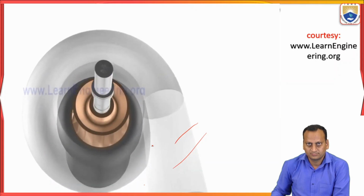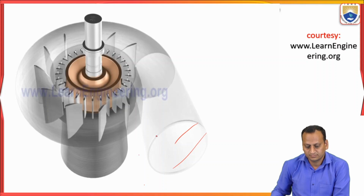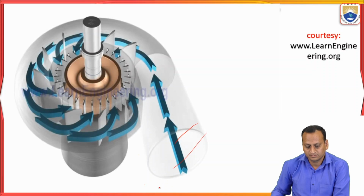Stay vanes and guide vanes are fitted at the entrance of the runner. The basic purpose of them is to convert one part of pressure energy to kinetic energy. Flow coming from the casing meets the stay vanes. They are fixed.